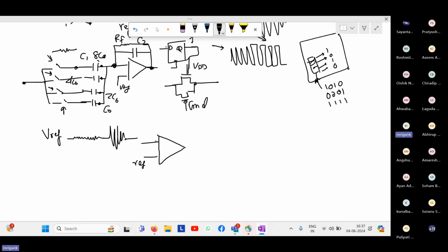So this is the signal coming to the comparator. Everybody understands this, right? The DC level of this signal will be close to VREF, because this is a feedback amplifier we have applied for amplification. And this will make sure that the DC level at the output of this amplifier is the same as the VREF because of the negative feedback.